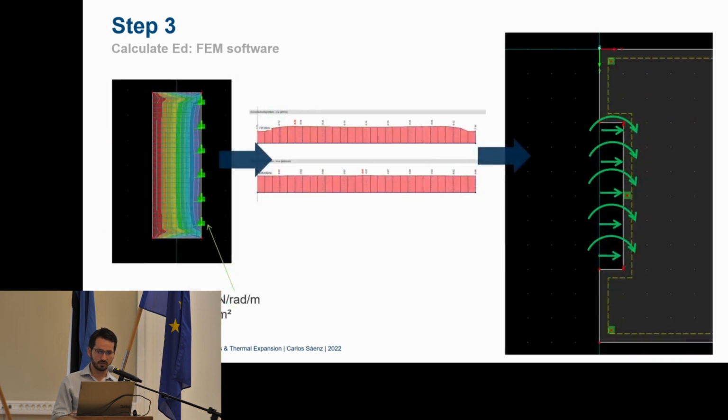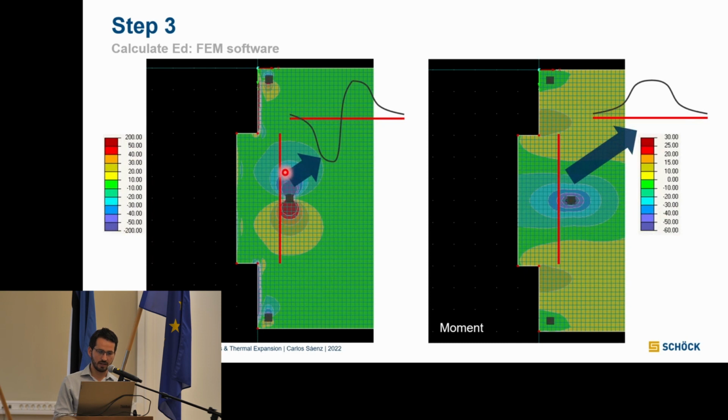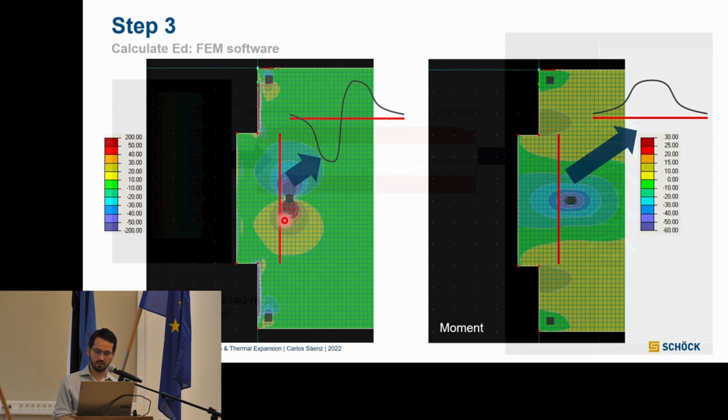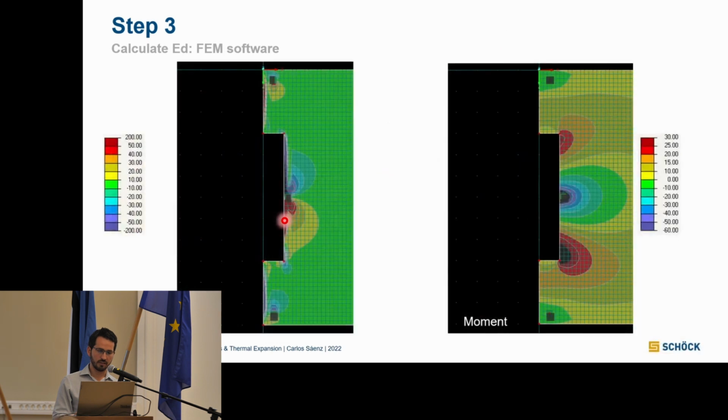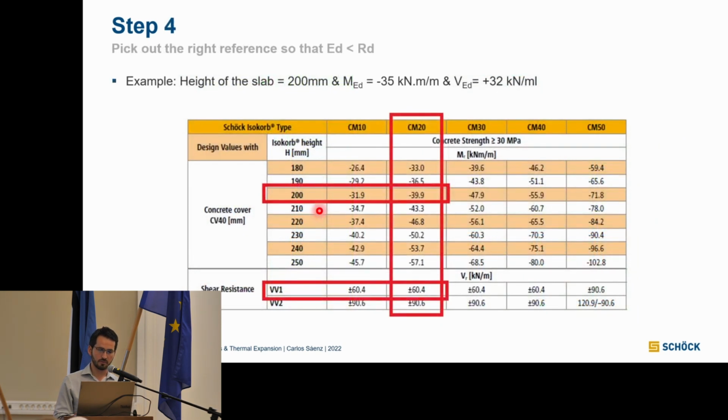If the analysis was made the other way, I have a bigger area to withstand those punching shear forces around my column. But in reality, I don't have that big area on this side. So just only 3 sides instead of 4. So yeah, the problem with that is you may end up under-designing your connection. So we need to take that into consideration.